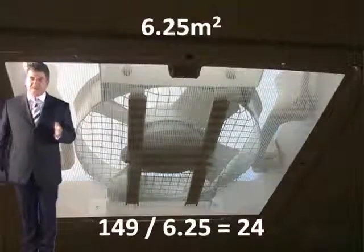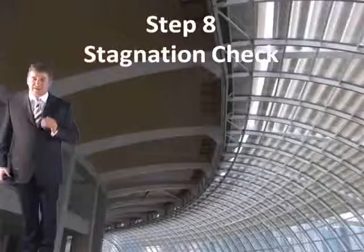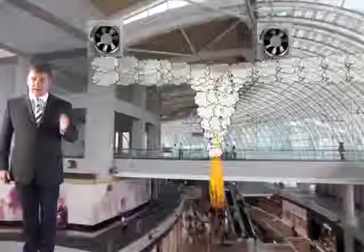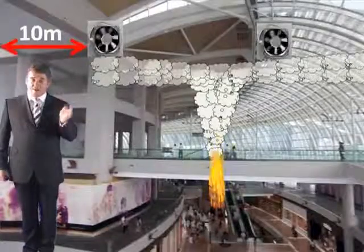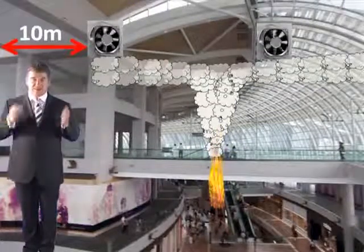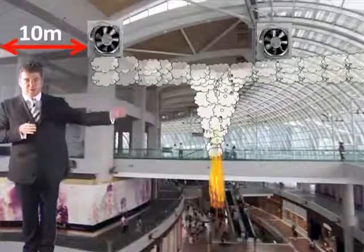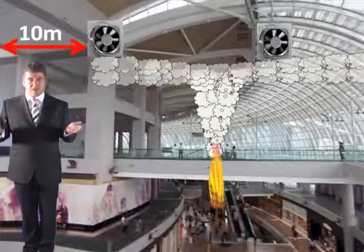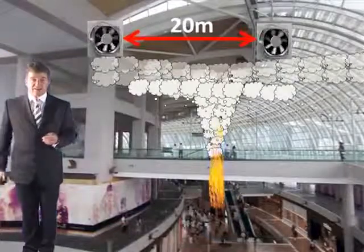Well, before you decide this, you've got to carry out step 8, which is the stagnation check. And what this is saying is ventilators should not be, for natural, should not be more than 10 metres away from an edge, and they shouldn't be more than 20 metres apart. So these are the key rules. You can't put a ventilator more than 10 metres from the edge of a reservoir, or have more than 20 metres in between the actual ventilators.